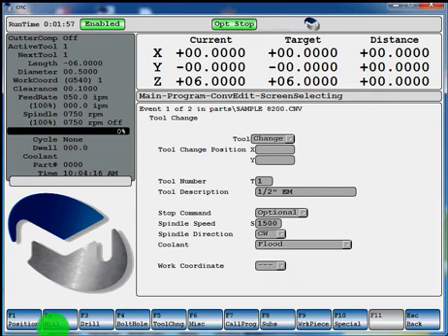And now you have all your different options of what operation you want to do. If you want to mill, drill, a bolt hole, do a tool change, miscellaneous functions. We're going to be doing a mill, F2. And are you going to be doing a pocket, a frame, a 3D pocket, threading? We'll just say we're going to be doing a frame, so we press F6.